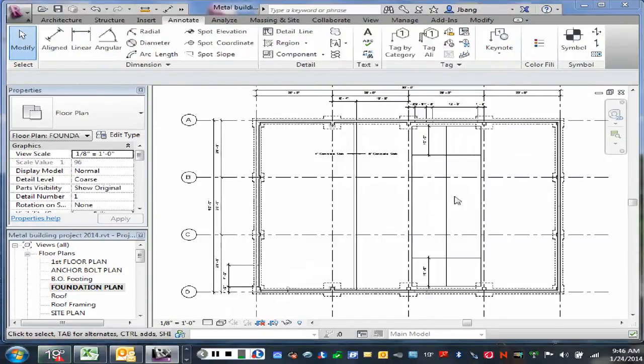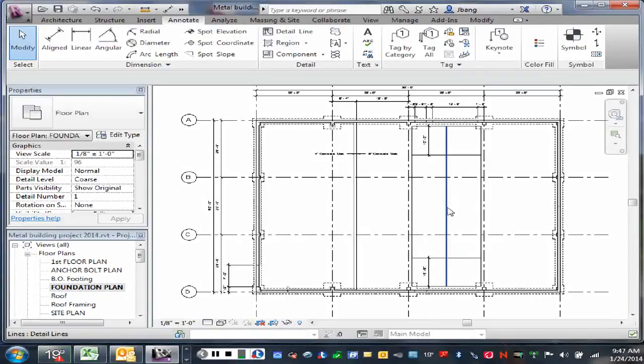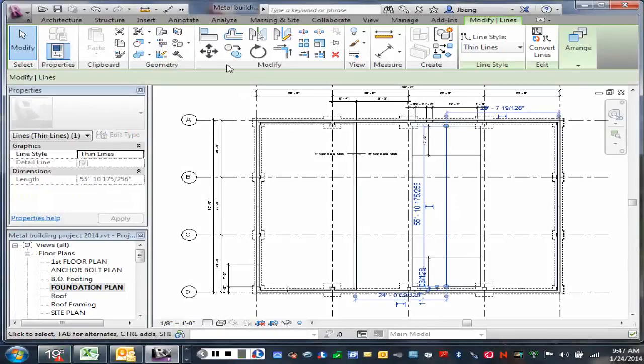Okay, on this center line, I want to create a flat spot in the bottom where the floor drain is going to sit. Now the floor drain could be a 6-inch wide floor drain or an 8-inch wide floor drain or a 12-inch wide floor drain. So there are different widths of floor drains. I'm going to offset this line 6 inches each way.